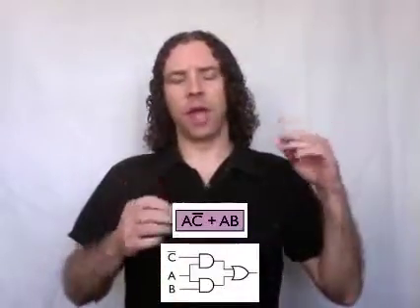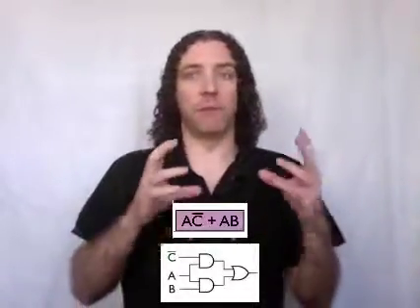So first of all, after I put in my inputs, how do I know when the output's done? Because remember, these things aren't instantaneous. The gates are actually some physical number of transistors, and transistors take a certain amount of time for their values to switch based on their inputs. So we have to put inputs into this and then just wait and at some point in the future read the output. But how do we know when that happened? And if we're trying to build a more complex system where something else now depends on this, or we're trying to store this somewhere maybe, how do we synchronize everyone? There's all these different components and nothing actually forces them to be in any sort of synchronized state.